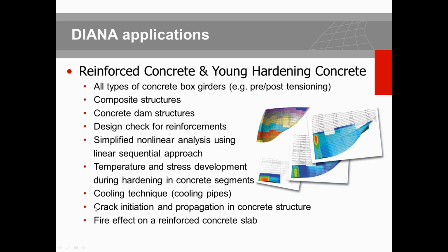And one of the key strengths is our embedded material models, which are dedicated to simulating different crack phenomena in the concrete. This crack initiation and propagation, we will go back to that in the next slides, enables you to identify the whole crack pattern, the crack strain, and also crack opening. Based on that, you can see the nonlinear failure and post-peak failure. That's the most important compared to other solutions that are available. Post-peak failure till complete rupture of the model.